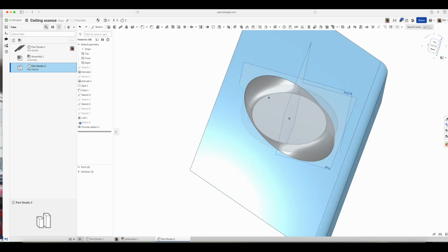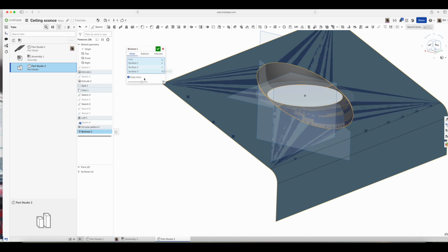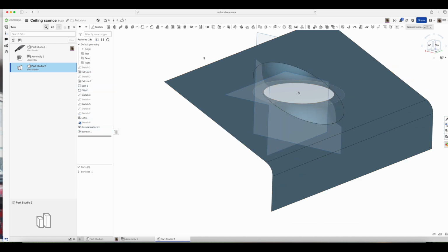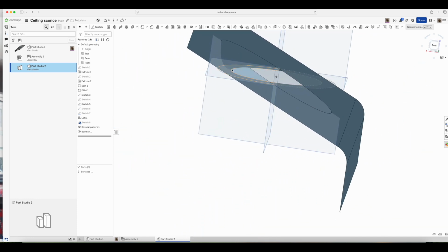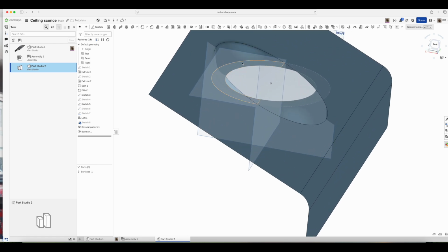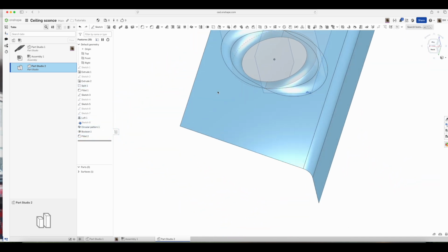So now we got that looking nice. And these are our main surfaces, so we're pretty much done. What we want to do now is Boolean these together. I don't keep tools when I'm Boolean unioning. And then what I want to do now is kind of add another little dip down. And so what we can do there is we can also fillet these to just add another nicer blend to the whole thing.